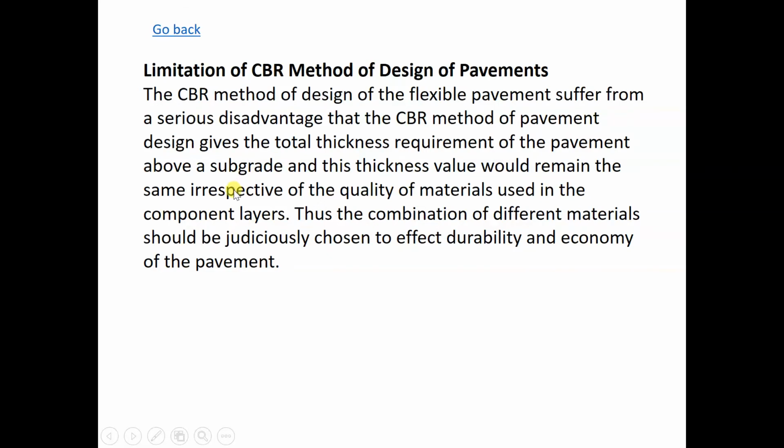They expect to provide the same result for the thickness, but the quality of material does make some difference: the durability, the weathering. So these CBR methods don't consider the quality of materials.